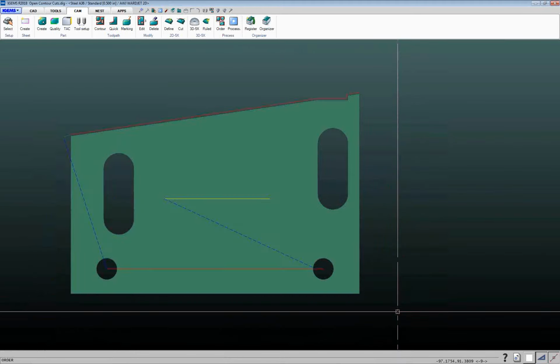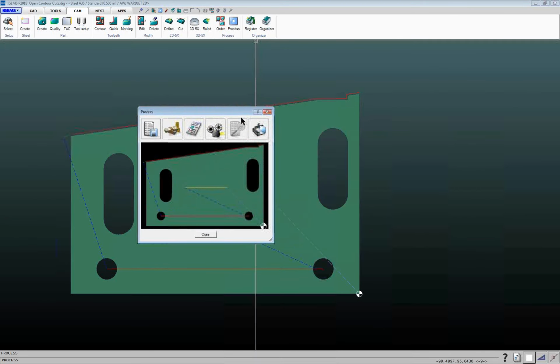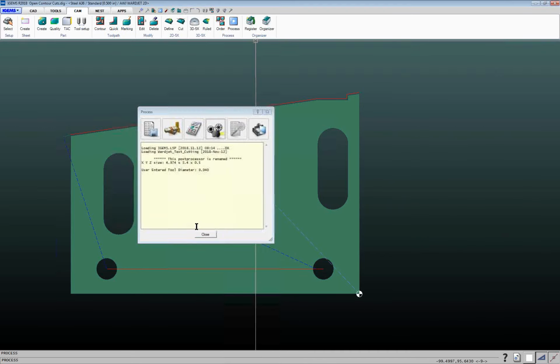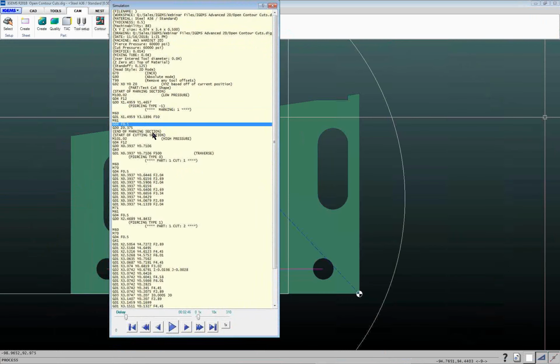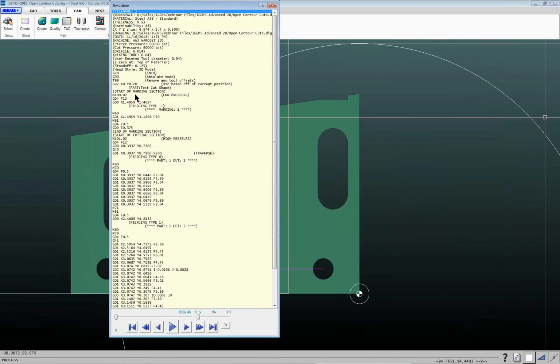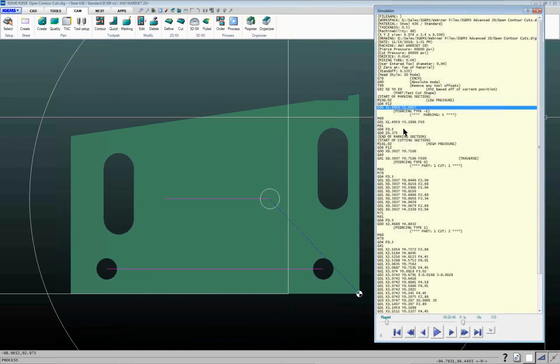If your pump has the capability, we can send signals to the pump, telling the pump to go automatically into low pressure and high pressure when it sees those different flags in the IGEMS part. So if we look into our code again, we've got start a marking section. So we've got a code here, tell the pump to go to low pressure. There's a delay to allow the pump to get to low pressure, traverses over to where it's going to do that mark, and then does that